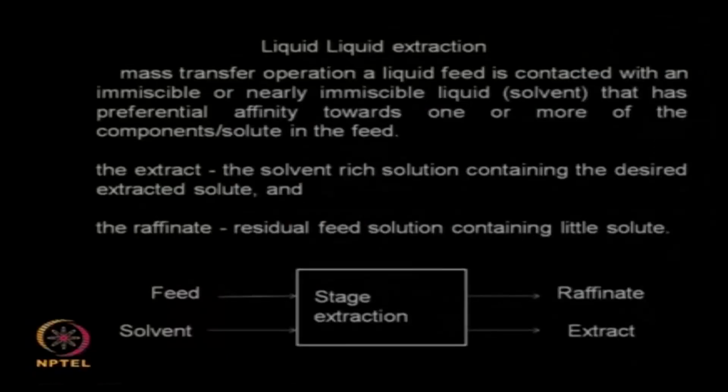So you have a liquid feed, it could be a fermentation broth or a reaction broth which contains the solute or metabolite or the protein which you would like to recover. You use a solvent, the solvent is immiscible or very sparingly miscible, and this solvent will extract preferentially the solute of your interest. You cannot say that only one solute will get extracted, because after the end of the fermentation broth you may have a large number of metabolites, so you may have some of the unwanted metabolites also getting extracted, but that is possible.